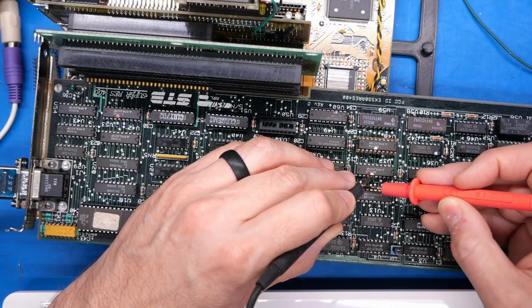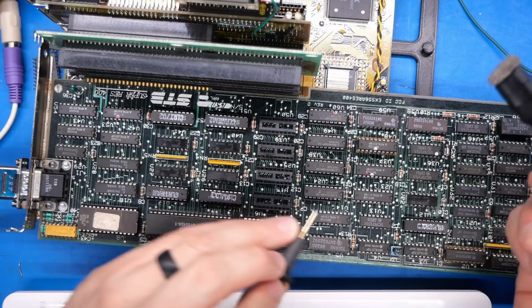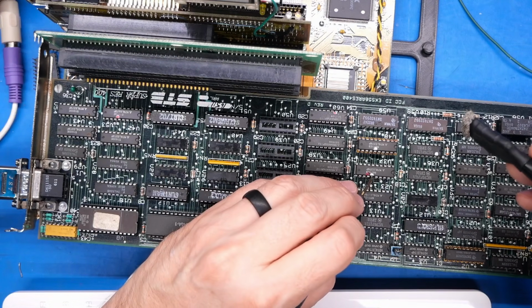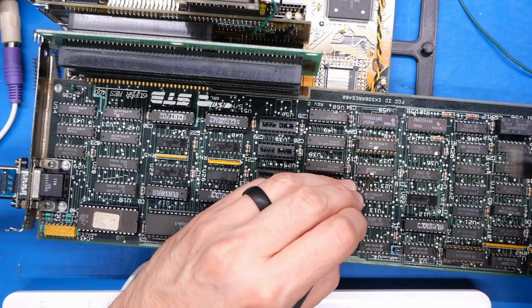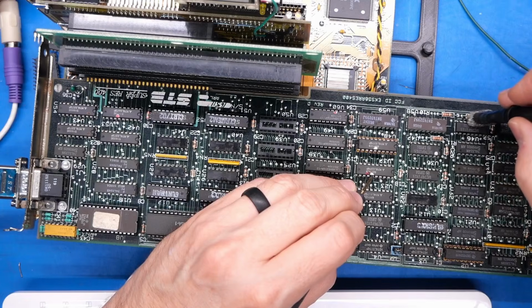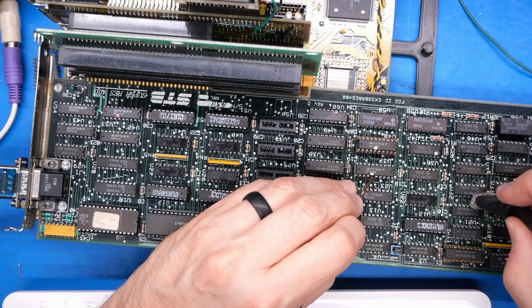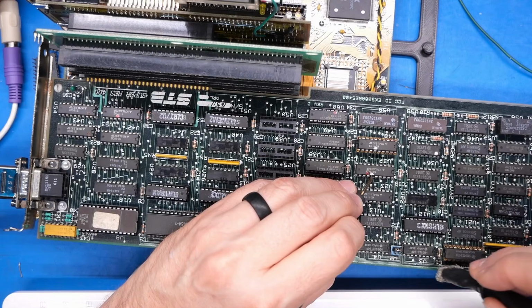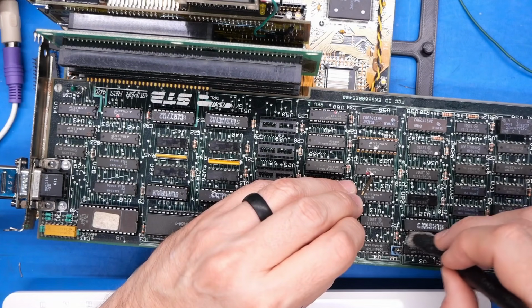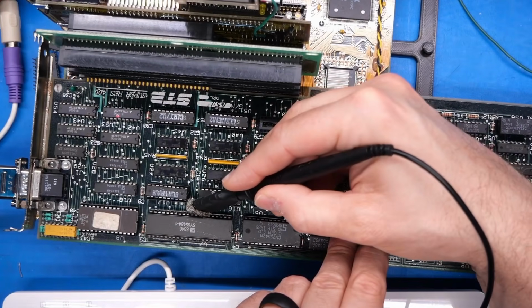It's kind of gotta. So one way to help find this stuff is to use these brush type probes, and we have that connected up there. So I'm on this pin here, which obviously goes there, and now I can just kind of go around the board like this and try to find where it goes. And then once you get to the area, you can use a more exacting probe to find exactly which pin it goes to. Okay, it's something over here.